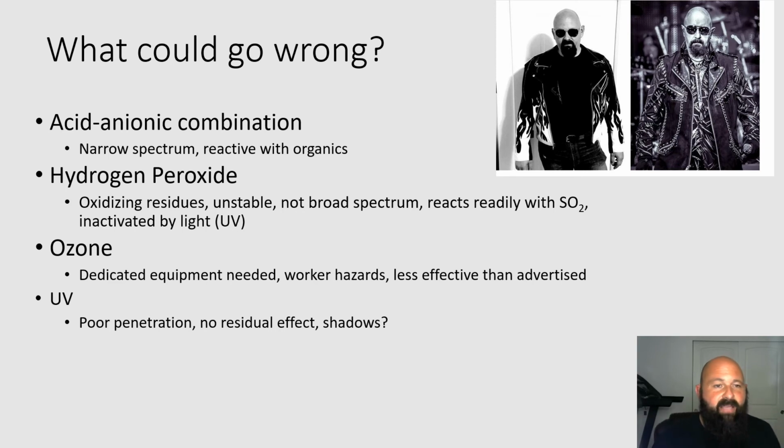We have issues with acid anionic combinations. They're narrow spectrum, again, reactive with organics. Hydrogen peroxide, oxidizing residues, it's unstable. Once you open the container, it's going to degrade pretty rapidly. It reacts easily with SO2, and it's inactivated by UV light. So not something that we want to use; it's very effective, but, again, it isn't the end all to be all. Ozone, again, dedicated equipment, worker hazards, less effective than advertised. Still, it works, but not the end all to be all. UV, poor penetration, no residual, shadows. So there are some things that can go wrong.